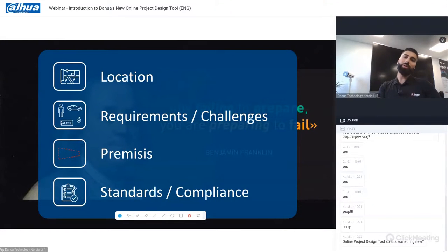So it's important that we understand, are there already some requirements from the end customer side for the PPM, the pixel per meter, or in some tenders, they will focus on DORI, which asks you to be able to detect, observe or recognize. In these terms, we are referring to the IEC standard that I was talking about.